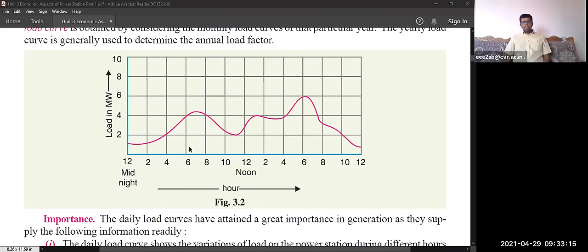Even in industries, they have to get permission for which hours they have to operate the machines. The substation itself will give a chart, a timetable, based on their loads, on which hours the particular machineries have to operate. They also have to give the machinery load: we have this many machineries, and we are consuming this many kilowatt hours.